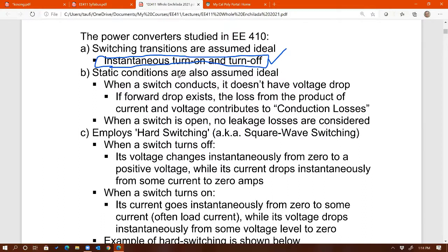So instead of saying, okay, duty cycle is going to be 0.5, you can say, okay, duty cycle is going to be around maybe 0.45 to 0.55, right? So that's something that you can use when you size components, right? Worst case calculations, right? Depending on whether or not the minimum or the max gives you the worst case. Does that make sense, hopefully? Right?